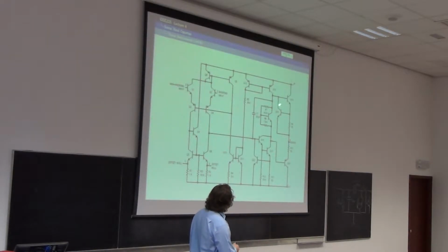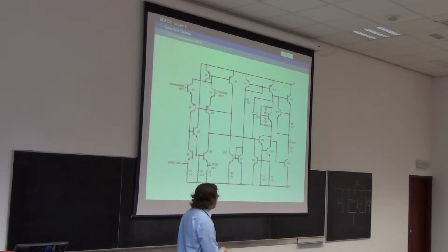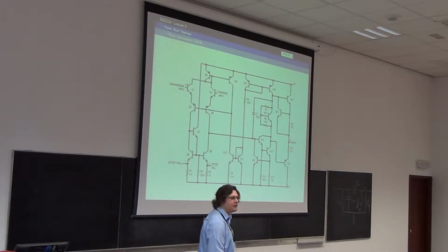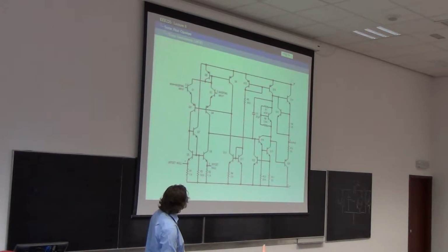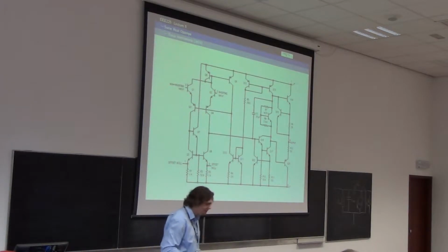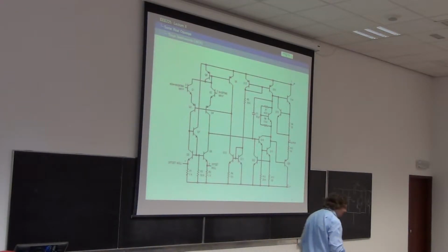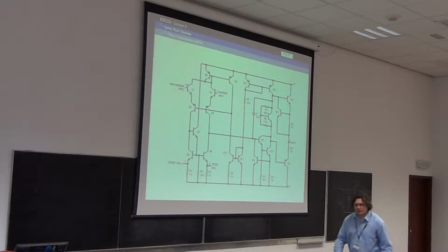The business of this transistor is to protect this transistor if we put an output on which is too low a resistance. And the way it does that, well, how does it do it? Any takers? Think about the current that flows in R9. So does it prevent like a too large ID going into that other transistor basically? Yes, it does. Why? Because like, well, it will turn on, won't it? Yes, it will. If there's a large current flowing, there will be a big voltage across R9. They'll switch Q50 on. Yes.